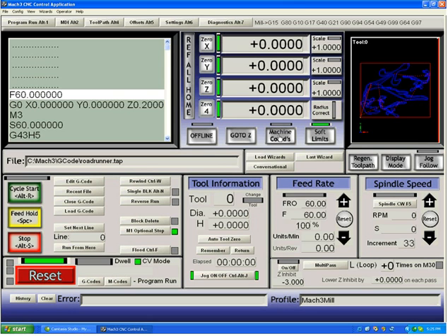Work offsets are also referred to as G54, G55, G56, G57, 58, and 59. G59 has a further parameter call which can turn on any of another 254 offset systems. You have a grand total of 254 offsets in the system. But for most users, you're going to be concerned with 2 only at first. As you get more advanced, you could look at the 3rd and maybe a 4th and a 5th. I doubt that most would go beyond 5. However, you do have immediate access in the program with a button to select up to 6 of them.